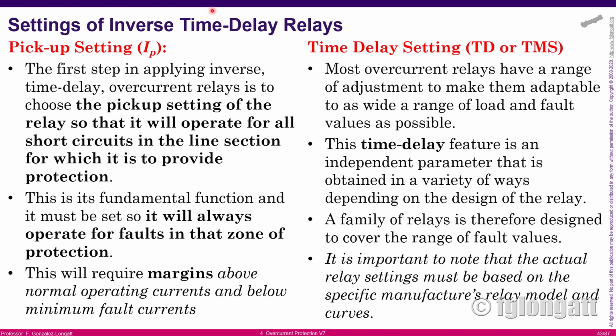need to do when we are working with inverse time delay relays. Okay, non-directional overcurrent relays with inverse time characteristic. Okay, what I need that you understand is that we need to set up the pickup, and that means the current when the device starts to work. Okay, on the other hand, the second setting that we need to take into account is the time delay setting.